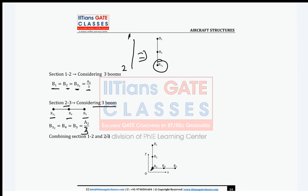Now guys, when I combine section 1 to 2 and 2 to 3, my idealized section looks like this. So here you have a bigger boom, because there is a contribution from 1 to 2 as well as 2 to 3 at the common junction. So you can see B3 is a bigger boom. My B3 boom area is B31 plus B32. Clear guys? Yes or no?